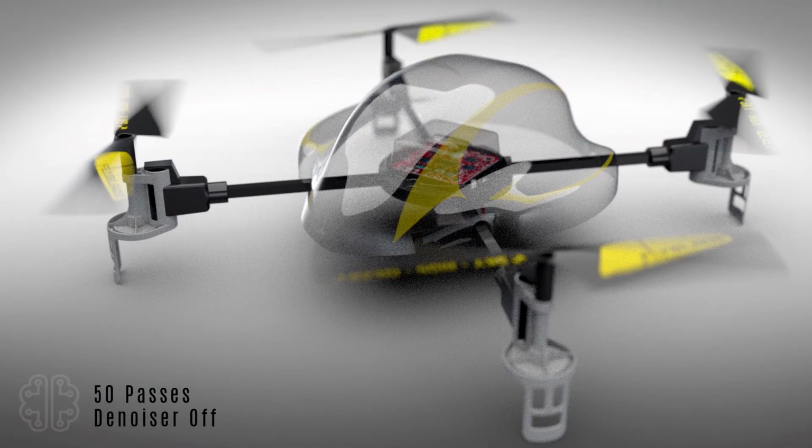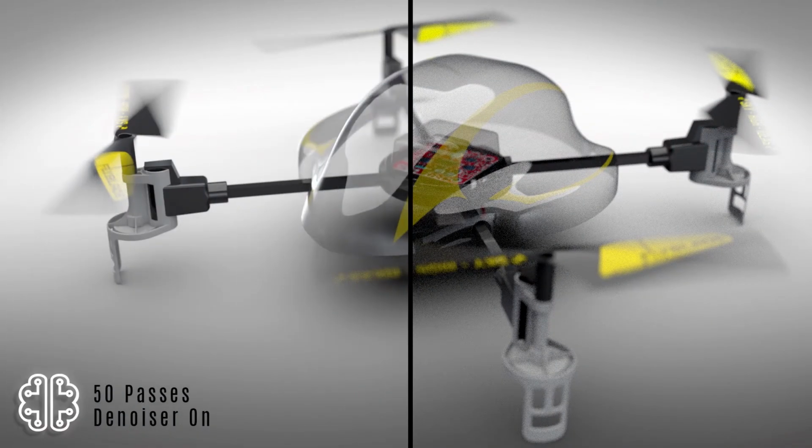Noise is a thing of the past as of SOLIDWORKS Visualize 2018 SP3. Now we have access to the all-new AI denoiser. Turn this option on to engage a smart filter that targets noise in your images. This is perfect for interior scenes, dark environments, transparencies, and shadowy areas. The AI denoiser results in noise levels that you would normally see if you had rendered the same image with 10 times the number of passes. That's right, with SOLIDWORKS Visualize 2019, you may be rendering up to 10 times faster. And that's just the start of the amazing enhancements that you'll see in Visualize 2019.